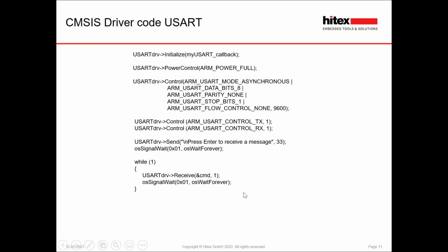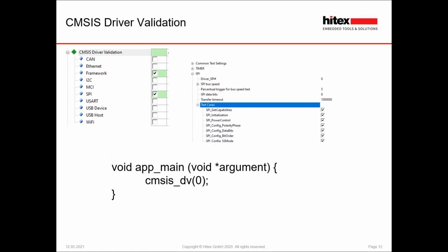Once you've learned this, it's pretty straightforward to use, and it will be the same for every microcontroller. Any code within our software component that's using the CMSIS driver API is very portable across lots and lots of devices. It means you don't have to spend lots of time writing and bringing up low-level drivers. You can use a CMSIS driver. If it doesn't have the features, there's nothing to stop you developing a more custom specific driver.